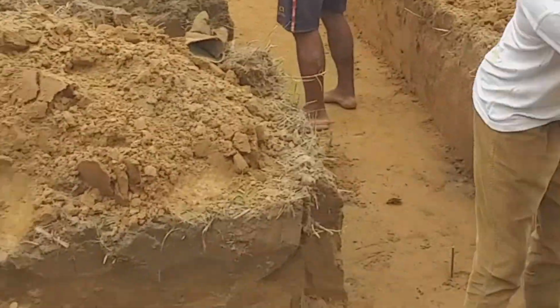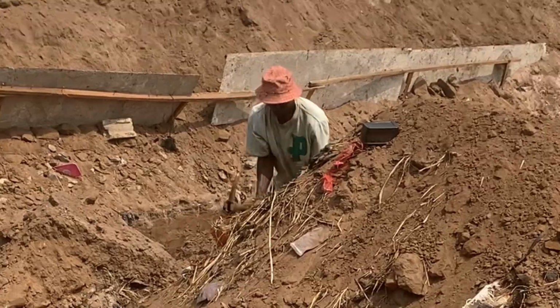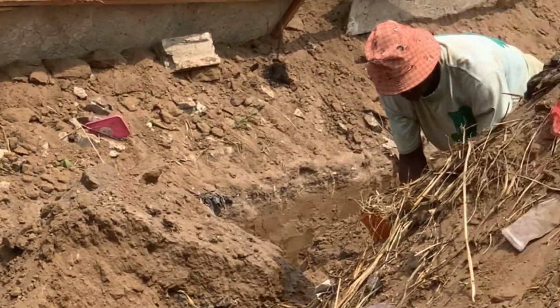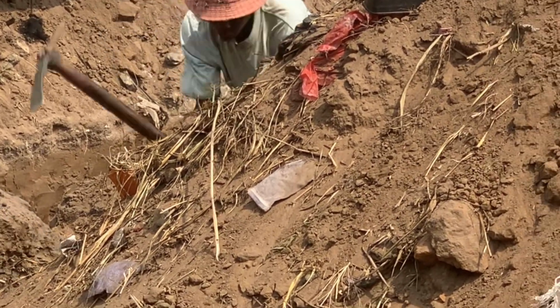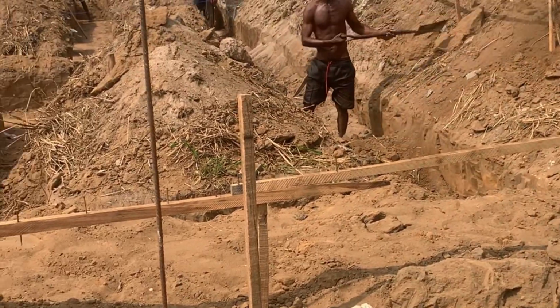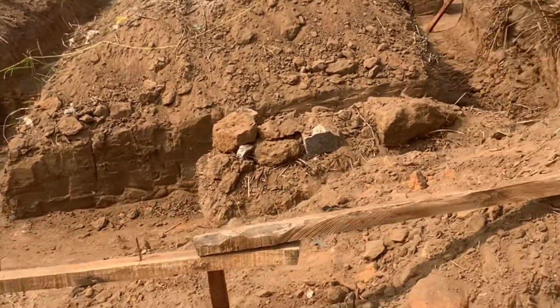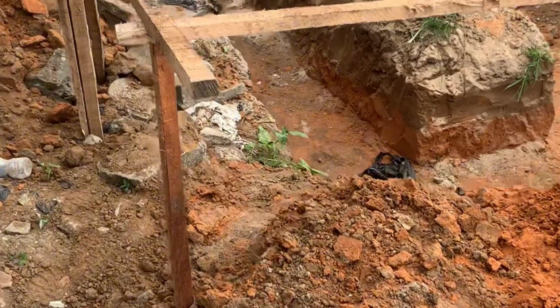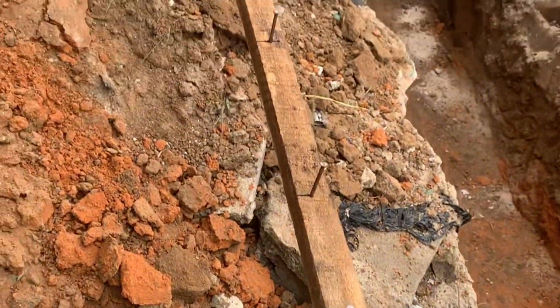Most times for small buildings, excavation is carried out manually with the use of simple tools like diggers, spades, and the rest of it. In the case of large buildings and deep excavation, mechanical earth cutting equipment can be used. Now listen, the depth of the excavation is gotten from the structural design, so it is not guesswork. It is already there in the structural drawings.